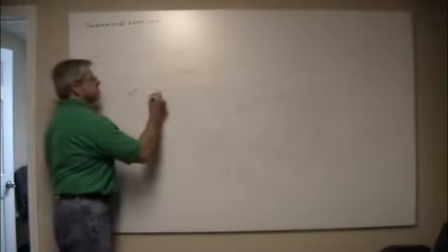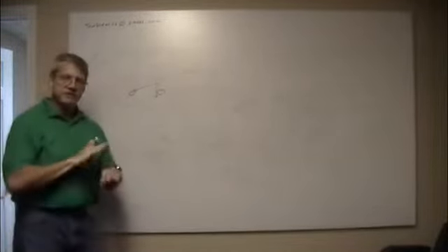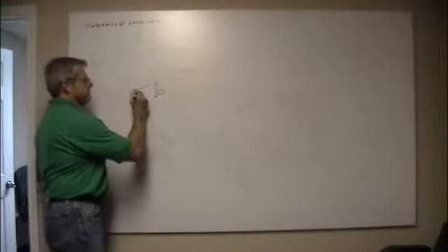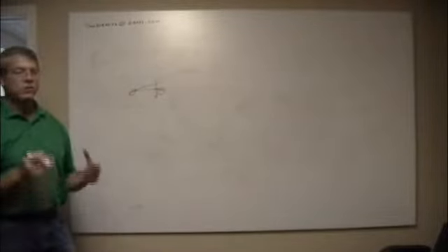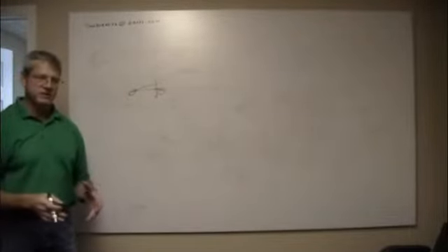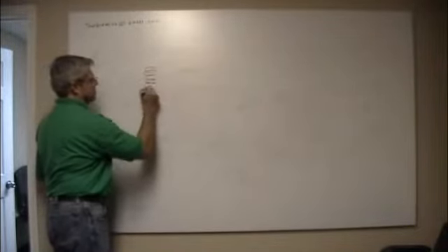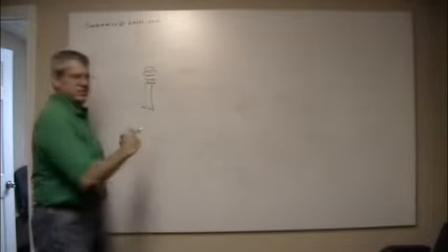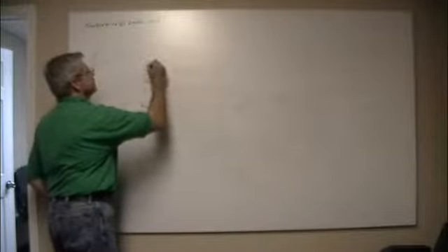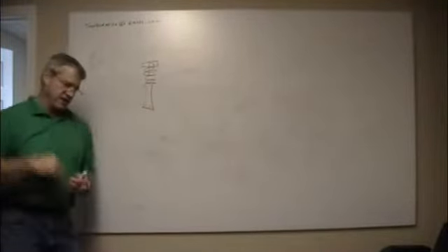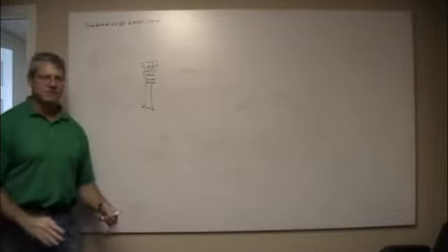When a switch comes closed, it's a mechanical device, and it literally bounces. So it comes in, it hits, and then it opens, and then it hits again, and it may happen 10 times. What they're doing with those contactors is they've got a big spring back behind the piece of metal. So you are pushing down on that spring and then finally it breaks over and bam! And the idea is to get as little bouncing as possible.